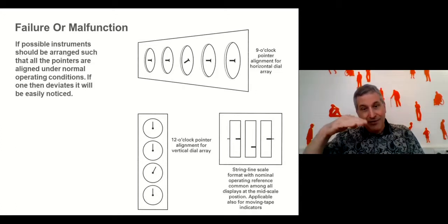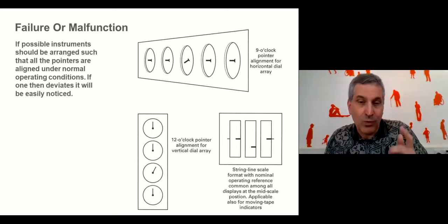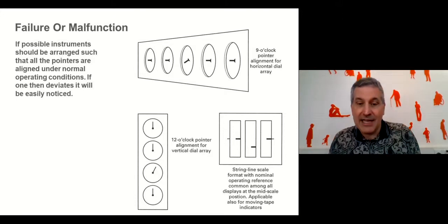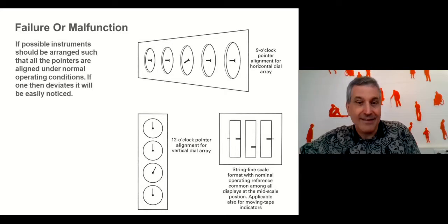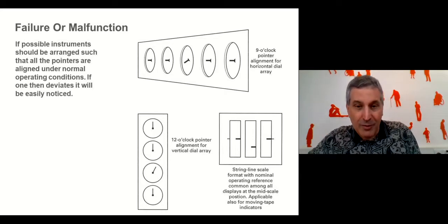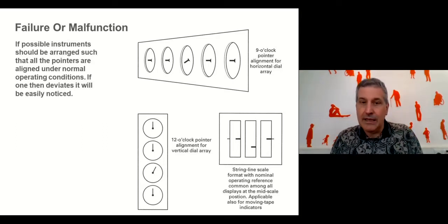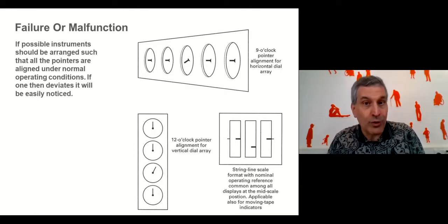If one of the indicators drops down or pops up, you can see all three examples show at least one doing that. When that occurs, it means that that particular measurement, that particular channel, the pressure of valve number 310 at the nuclear power plant, that particular sensor being displayed on that display has deviated from what the designers expected it to normally do.